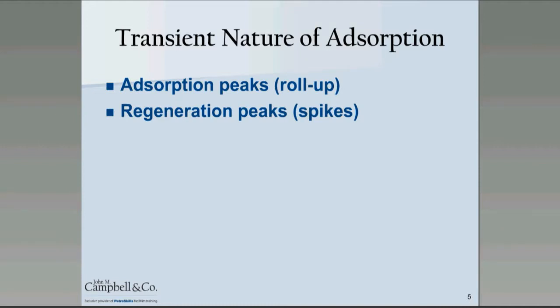This displaced H2S or ethane results in an increase in concentration as it rolls down the adsorption bed. This increase in concentration translates to an increase in partial pressure. This, in turn, increases its adsorption capacity. So any displaced hydrogen sulfide will load up on the active material further on down the bed. And if you continue this process, where the water will continue to desorb, let's say, the hydrogen sulfide, in the end, the H2S that leaves the bed during adsorption will have a higher concentration than it did when it first entered the bed. This is called a spike in the outlet concentration.